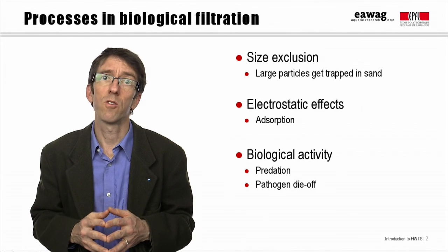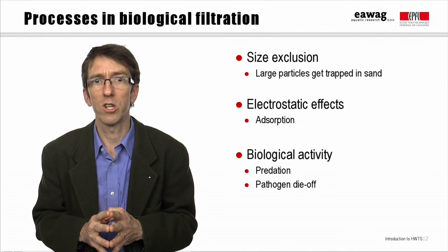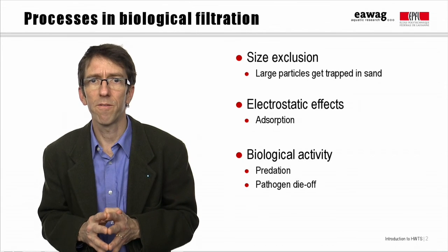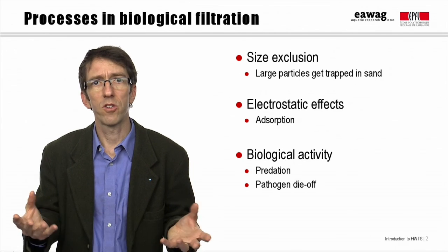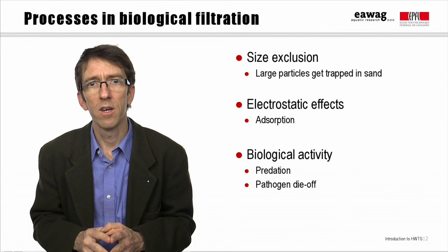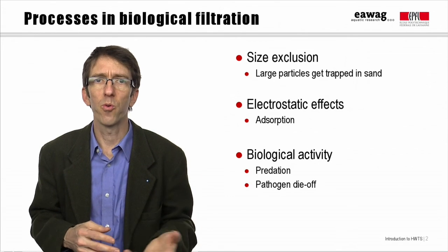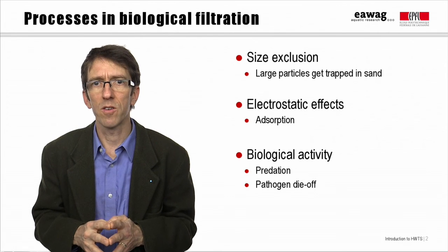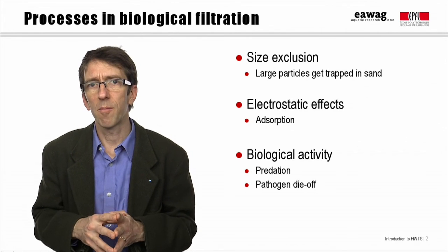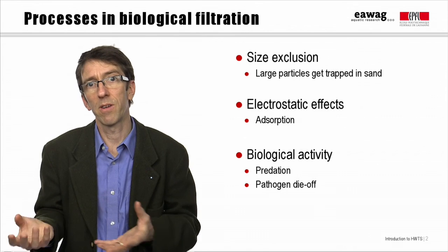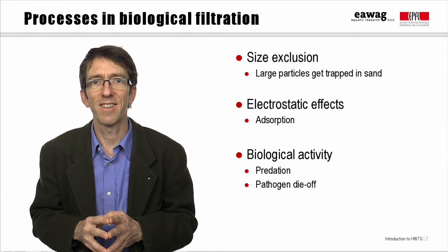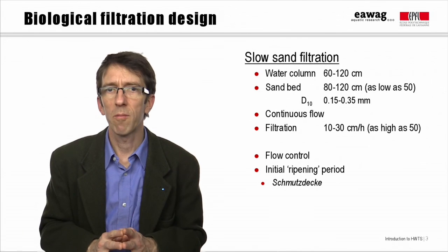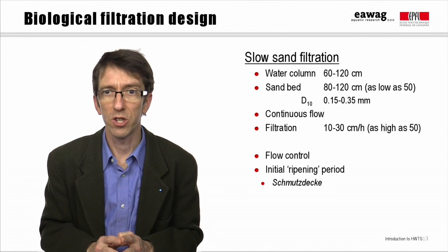Biological filtration is also much slower than rapid sand filtration, and there also tends to be a long residence time within a filter where some of the pathogens will die off naturally due to lack of food or oxygen, or the temperature is not convenient, because they're mostly adapted for living in the intestines rather than in a sand filter in someone's house. Let's look at some design parameters for conventional slow sand filtration.